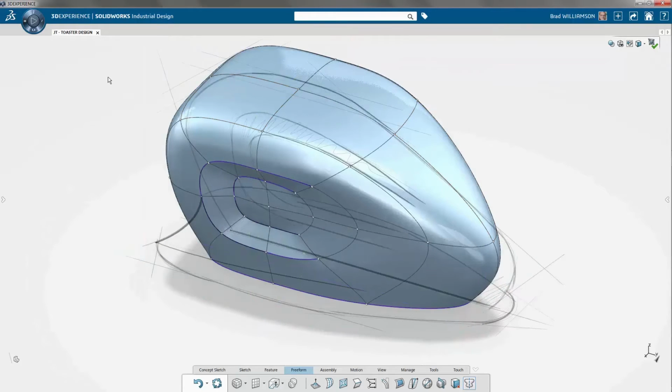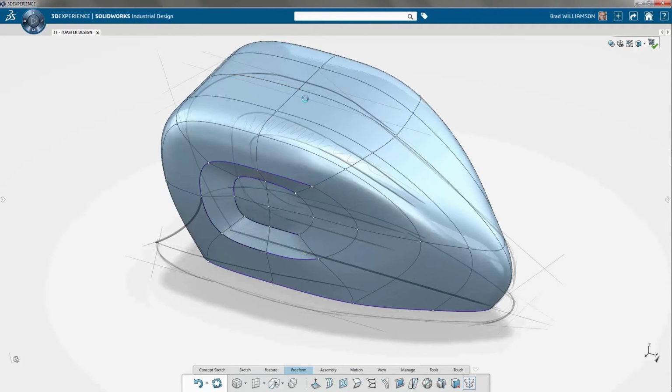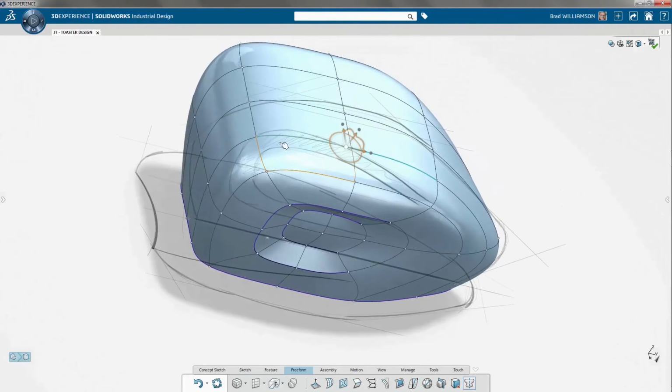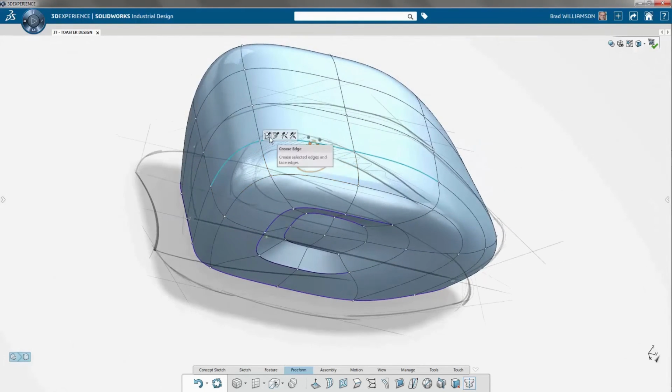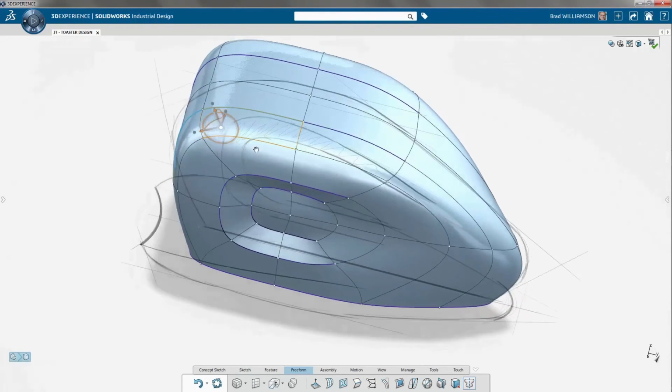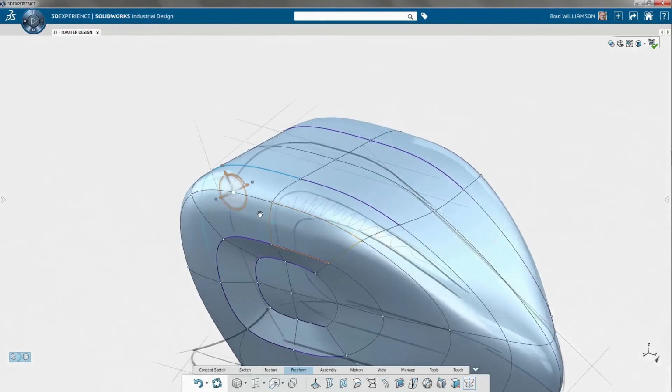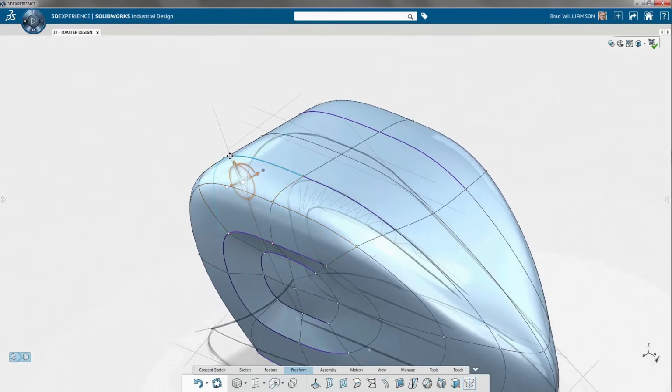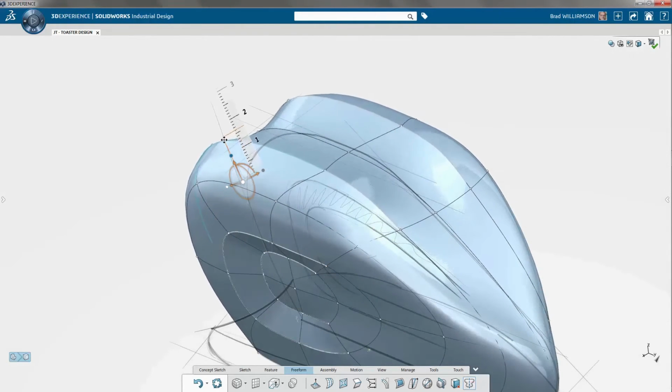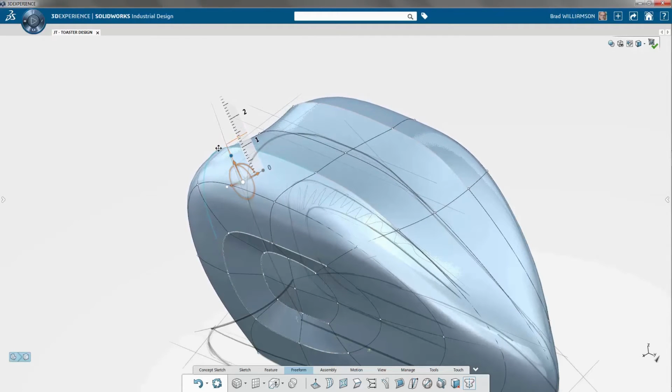Along the top of the tank, I'd like to create a ridge that bulges out slightly from the leading profile of the tank. I'll begin by adding a loop, which will give me some extra edges and control points to play with. I'll crease 3 of the new edges, then use the drag handles to scale them outward just slightly. Notice how the sharp and the smooth edges blend together without any extra effort.